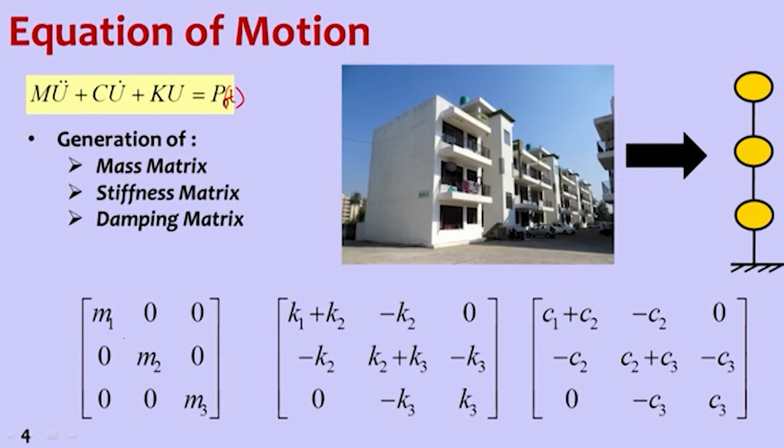In the stiffness matrix, K1 plus K2, you can see there are off-diagonal terms. So, we can call this coupled in stiffness and coupled along damping, while it is uncoupled along the mass matrix. In simple words, when we write these 3 equations of motion, one for each point mass, we cannot solve these equations independently.